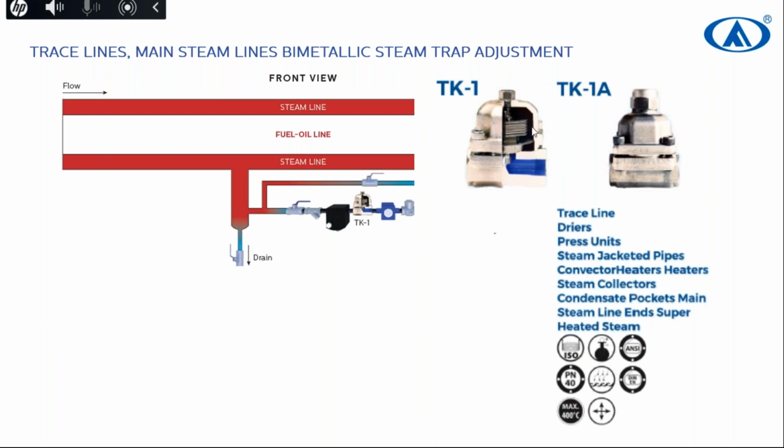SK70 right now has a delta pressure 21 orifice. It means up to 21 bar differential pressure, you can use SK70 from size DN15 to DN50. SK70, the forged steel body type, goes up to 25 bar.